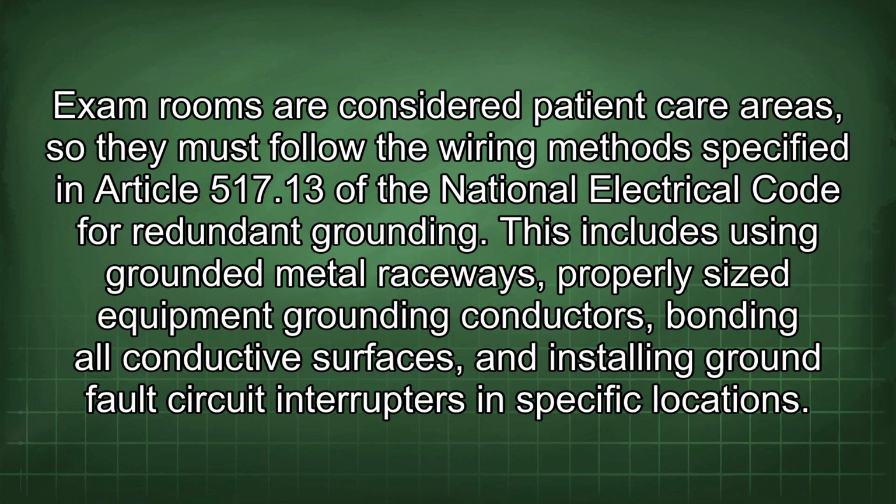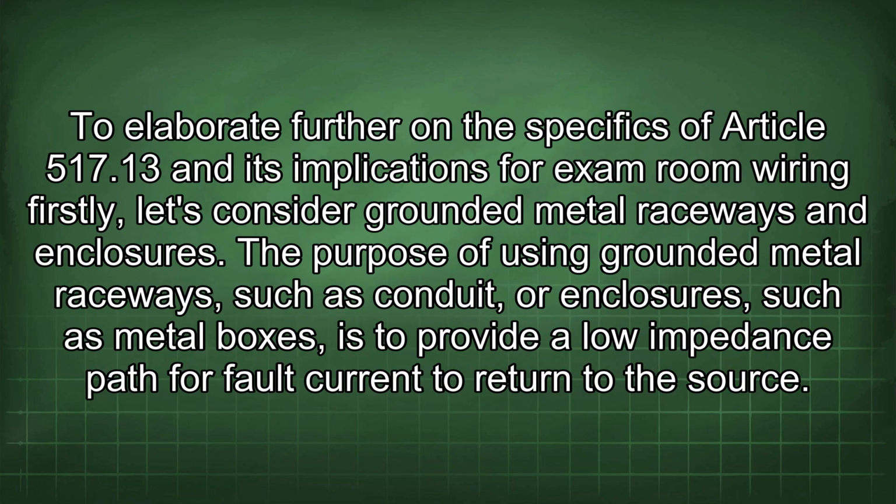Exam rooms are considered patient care areas, so they must follow the wiring method specified in Article 517.13 of the National Electrical Code for redundant grounding. This includes using grounded metal raceways, properly sized equipment grounding conductors, bonding all conductive surfaces, and installing ground fault circuit interrupters in specific locations. To elaborate further on the specifics of Article